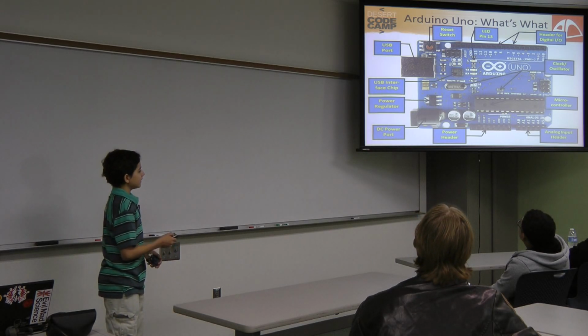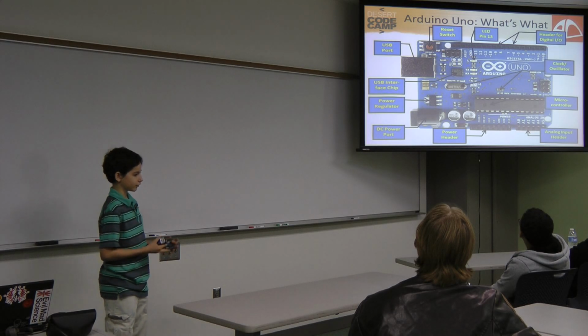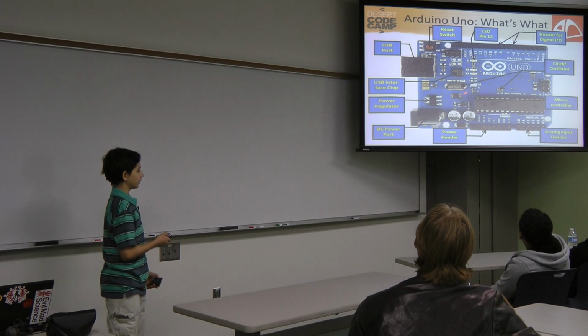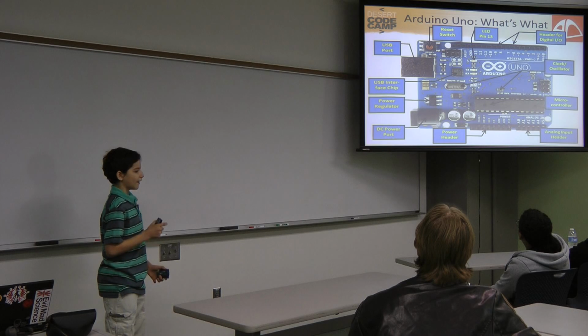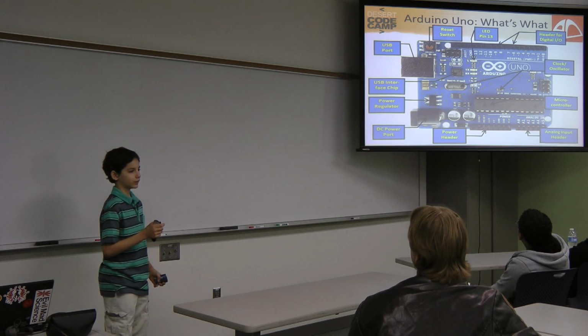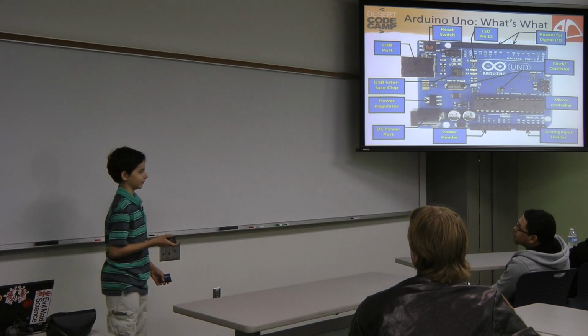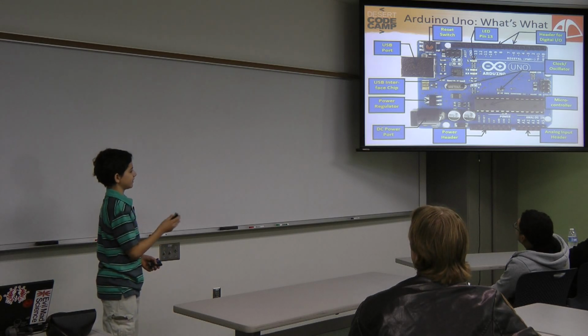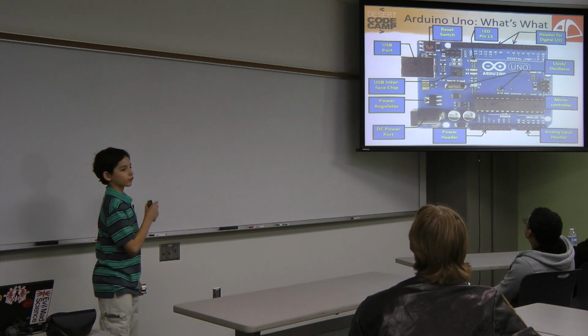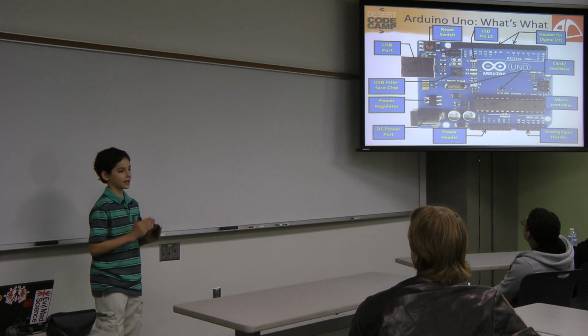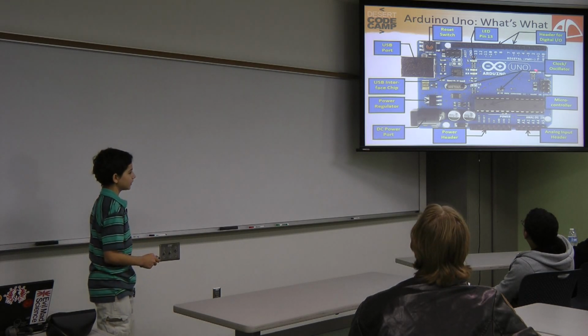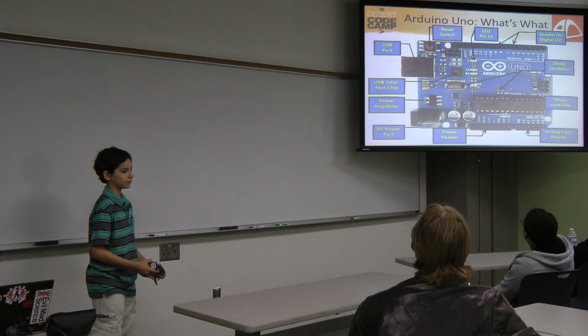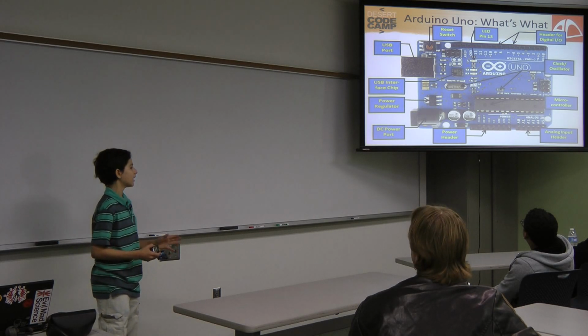These silver things here are the clocks or oscillators for the Arduino. The big silver one here is for the USB chip. That actually uses a quartz crystal, which looks like a piece of glass. I've opened one up. They're both at 16 megahertz, except that one is a quartz crystal because it needs very accurate timing for USB. This one here is a ceramic resonator, so it's less accurate, but it's good enough for the ATmega328.